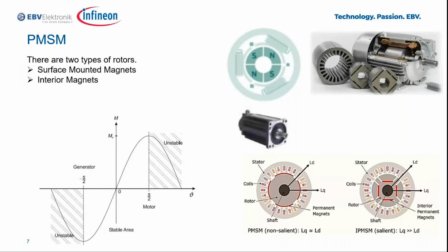If the excitation current is constant, as in our case in the PMSMs, then the load torque will determine the load angle theta. If the two fields are perpendicular, like 90 degrees, the highest torque is produced. That is the key case. If the two fields are aligned, no torque is produced.